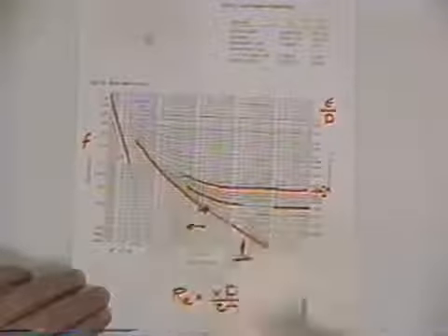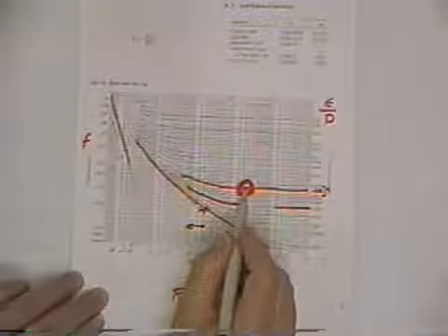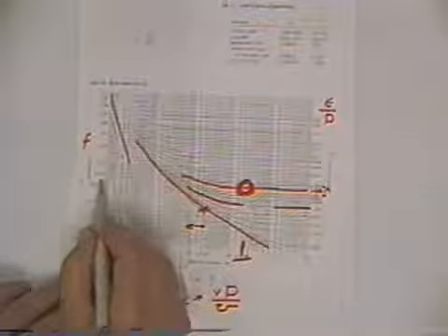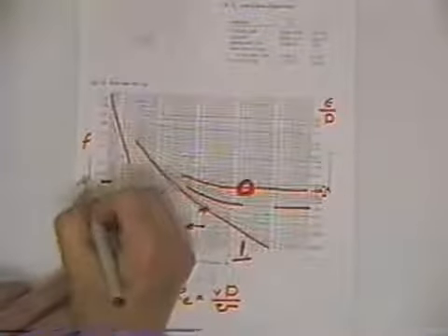There's a 0.001 and there's a 0.002, so it's got to be in there someplace. You've got to eyeball it and do a little interpolation. I'm looking for 0.0017, so it's between those two someplace, like so. I've got the Reynolds number, and it projects up, so we're right in there someplace. Having found that point, we read across to right over here, and we get a friction factor of 0.023. So the Moody diagram served its purpose.